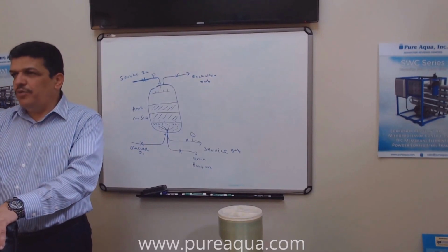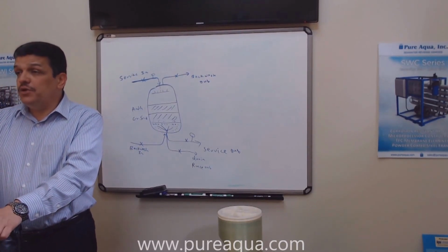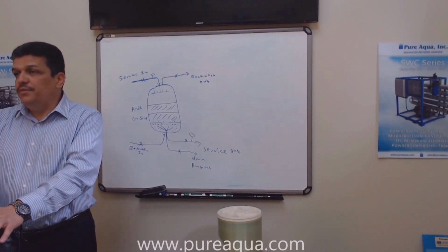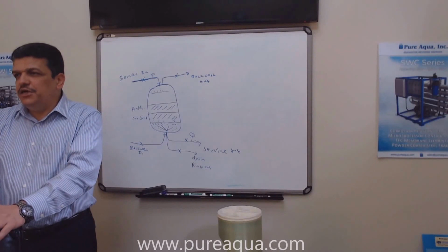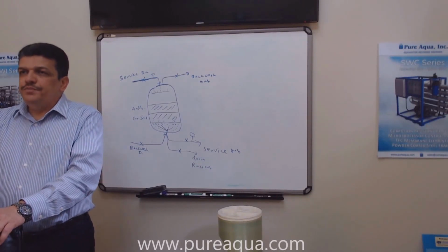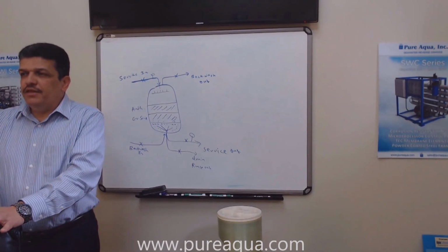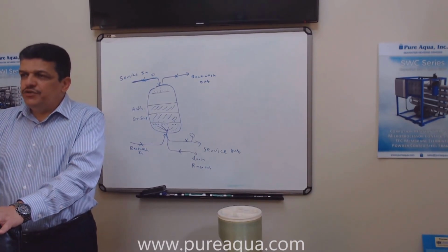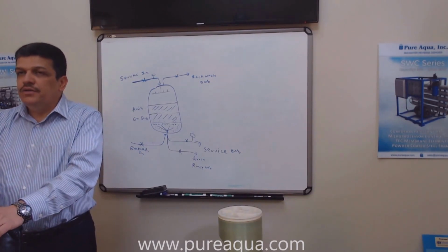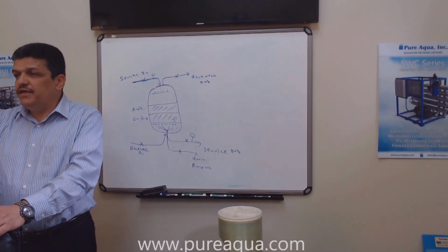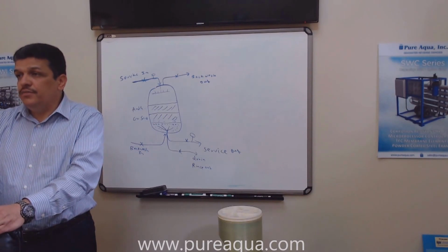We're talking about iron and manganese. The manganese is way stronger than the iron. It's really, really nastier than the iron. Very nasty. So when we do the iron load, we assume the manganese has double the strength of the iron. Whenever you have half a ppm of manganese, it's like 1 ppm of iron. It's very, very nasty.